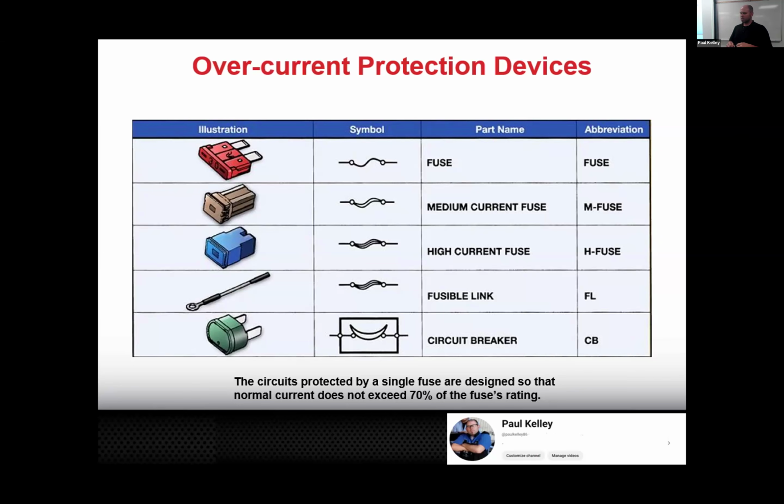And the way that you test them, you could test some of these with your meter, but the way you test a fusible link, actually, you grab the wire like this and you pull on it. And if it's a wire inside, you feel it's tight. But if it's a fusible link and the wire has burned up, all that's left is the gummy insulation. You'd be like, oh, that fusible link is bad. But now what do you have to do to fix it?